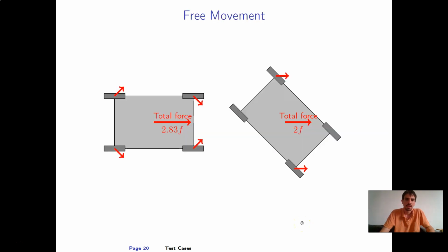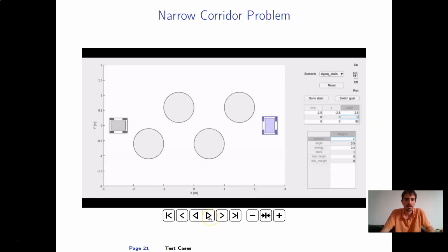These behaviors can be explained by studying the forces on the robot. When moving horizontally, the total force is greater, so it makes sense to accelerate horizontally. However, as we mentioned at the beginning, this also causes some energy to be lost in the form of competing forces. Therefore, once the system has finished accelerating, it is best to move diagonally in order to avoid this energy loss.